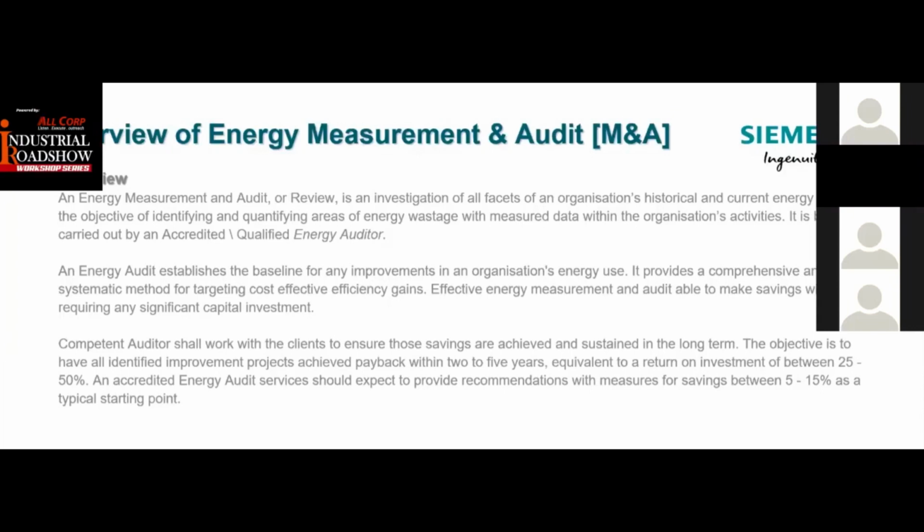And this system is based on the energy data that's been collected and the system installed within the building. So an energy audit is not a so-called standard practice report you can just duplicate from building to building. It's actually unique for every building, every facility, or every premises. And what we are trying to do in an energy audit, end of the day, is find facts and data, understand the building, understand the system, to explore areas or room for improvement.